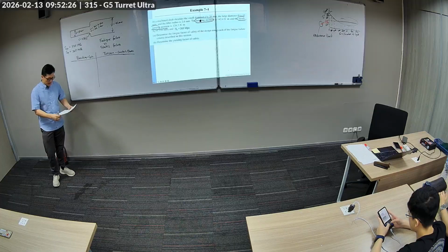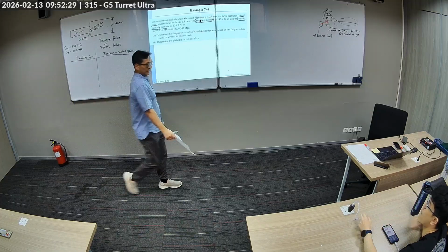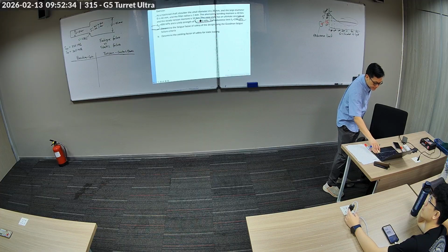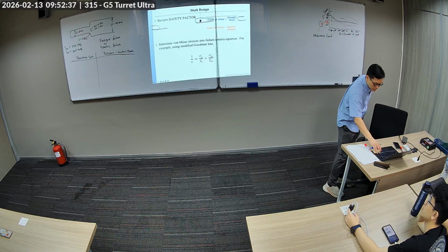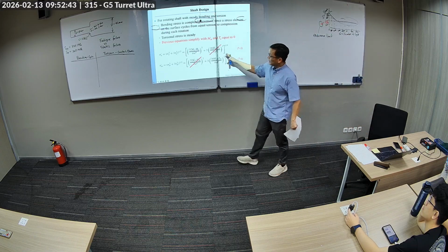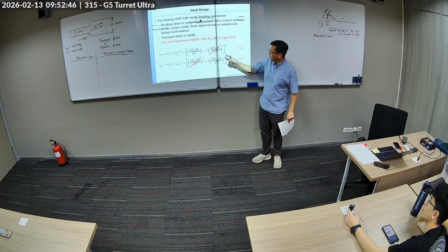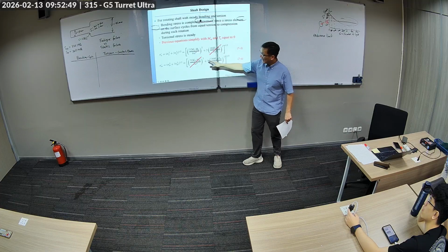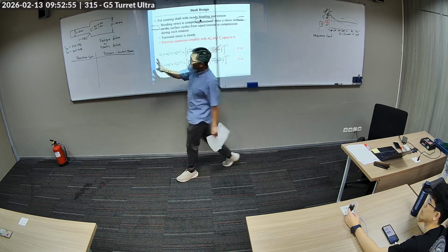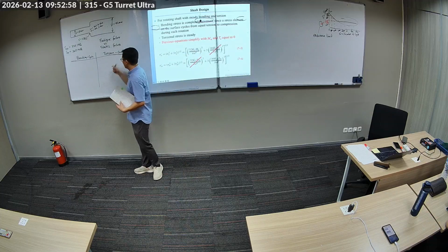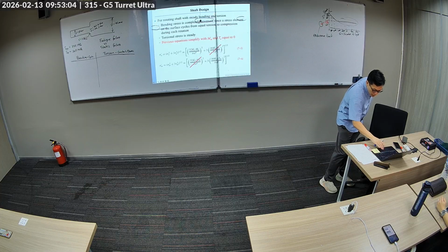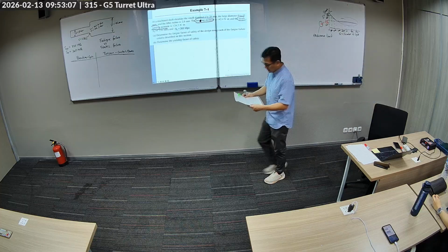And you will be given formulas that contain both, but you can actually strike out many of the terms. So this formula becomes simplified because the alternating torque and the mean moment are zero, because only the bending creates cyclic loading, but the torsion does not. Okay? So that's why I need to talk about that.